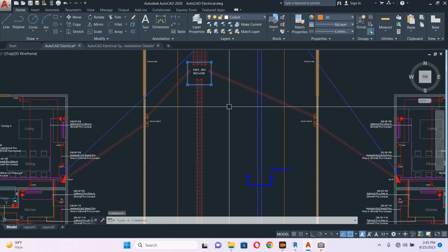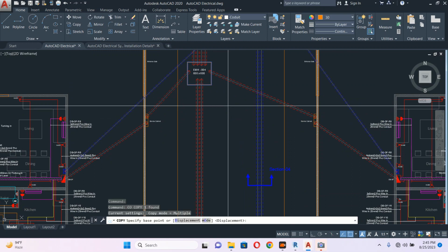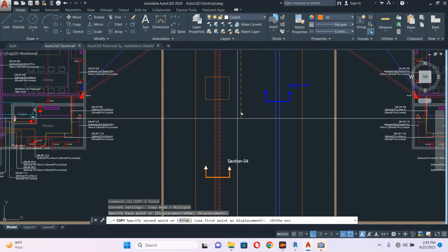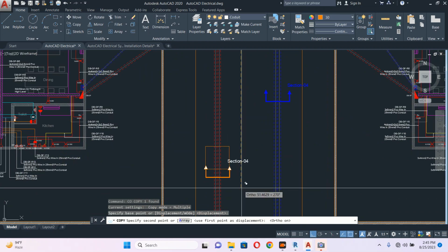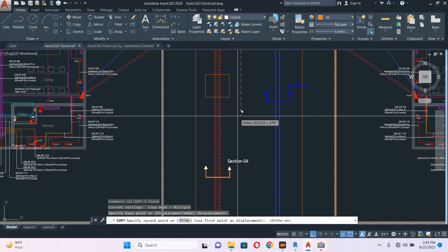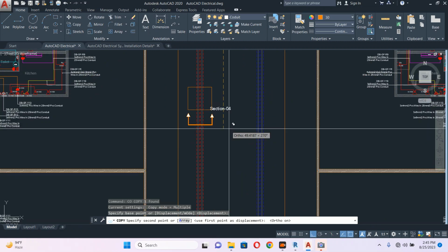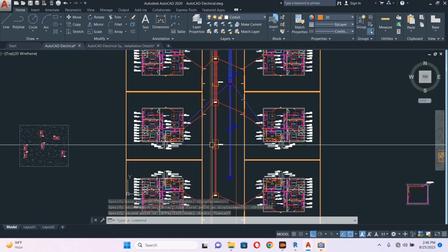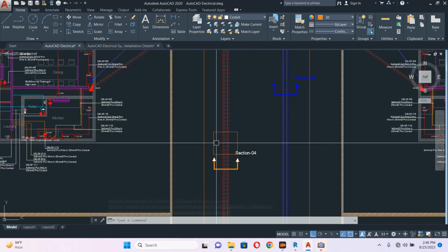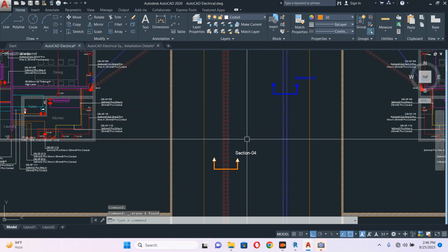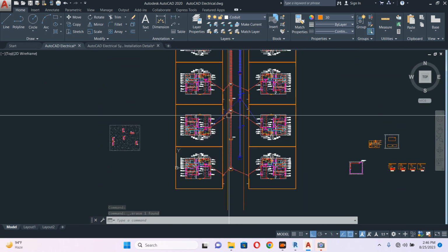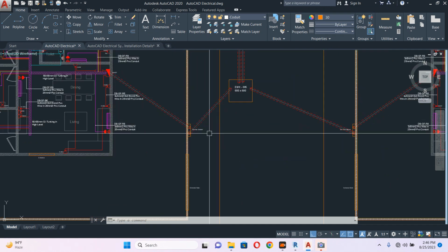For example, this manhole here, you should notice this one. It cannot be here somewhere. Or 90 degree, it's possible, but still better to avoid 90 degree like this. Meaning the cable will come like this and go up, so it is difficult to bend. But here coming like this and going like this, very easy.